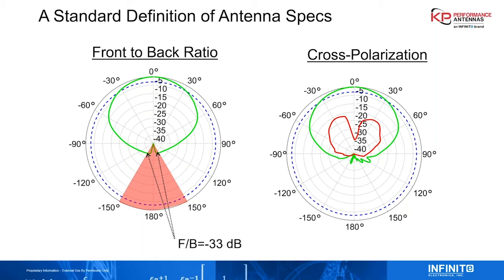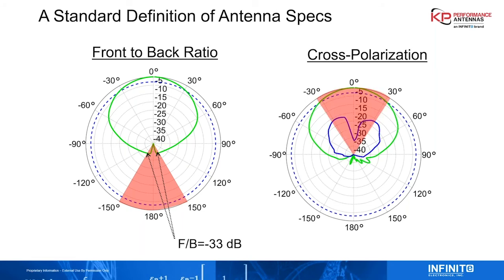across your entire sector. But a lot of the times the definition of cross pole is only defined at 0 degrees right at the main beam. But like I said, you use this across a whole sector, and you really care about the difference in cross pole across that sector, which is 18. Now 18 is actually really good. I've seen it anywhere down to 10 or 5 dB, and MIMO is still working fine. So just another example of how the definition plays a huge role in the spec that you're going to see in the field.